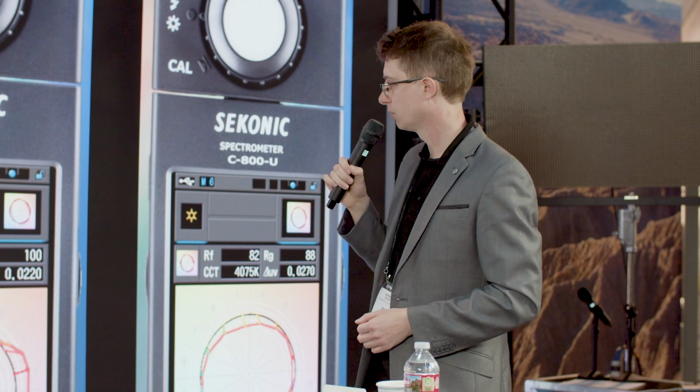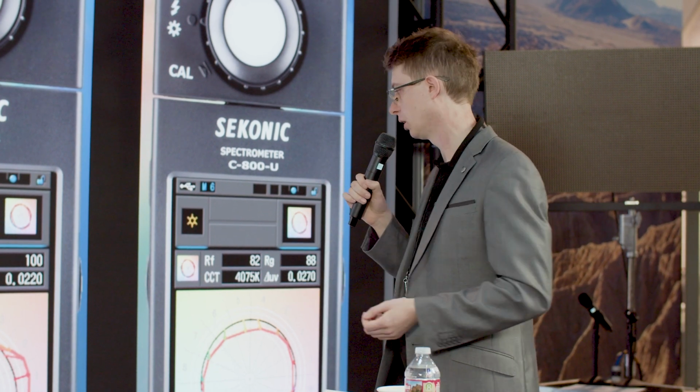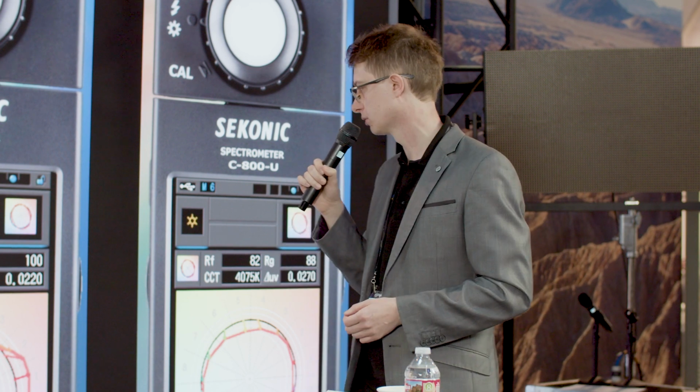Finally, on the right-hand side, we can see some TM30 measurements, a rather more modern color rendering metric. And for those who are familiar with TM30, our fidelity score goes from around 60 out of 100 to 82 out of 100, a very meaningful improvement.